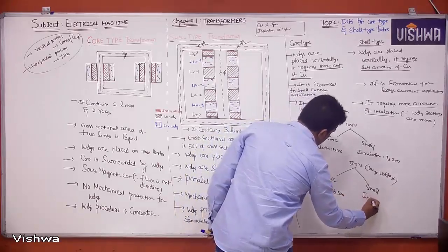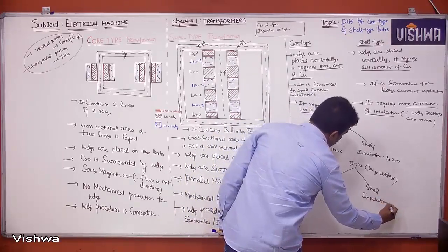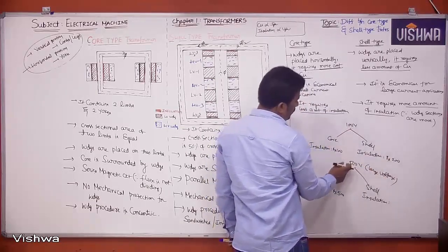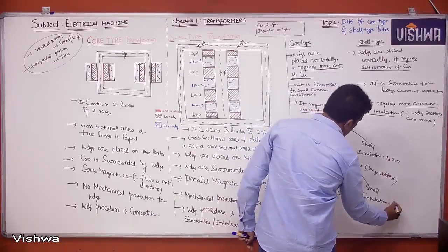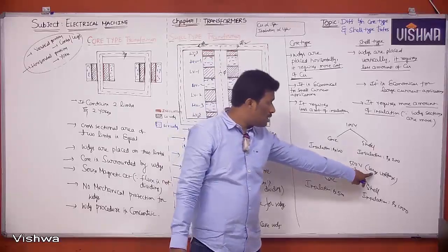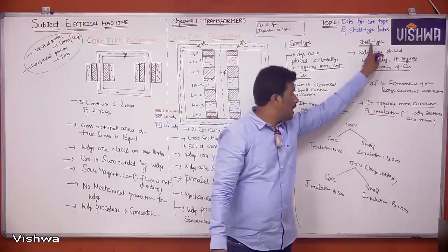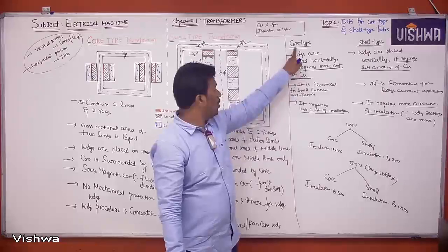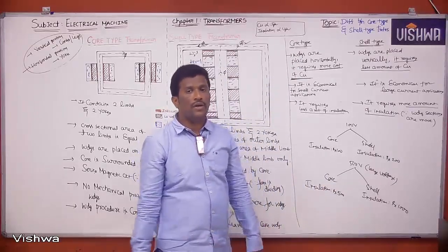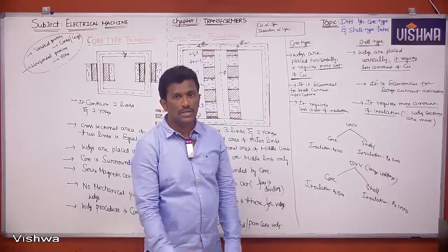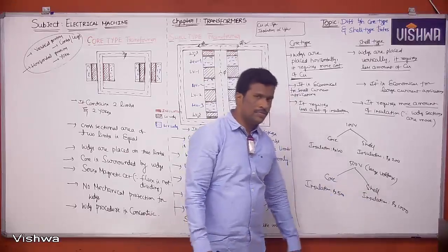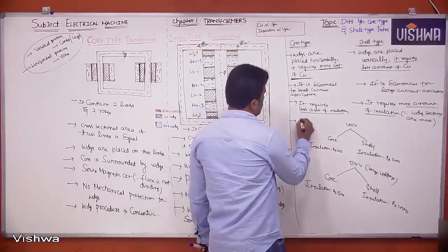Whereas in shell type, 100 volts meant 200 rupees, so times 5, approximately 1000 rupees. So for large voltage applications, shell requires 1000 rupees and core requires only 500 rupees. Therefore, obviously core is economical for large voltage applications, because 500 rupees here, 1000 rupees there.